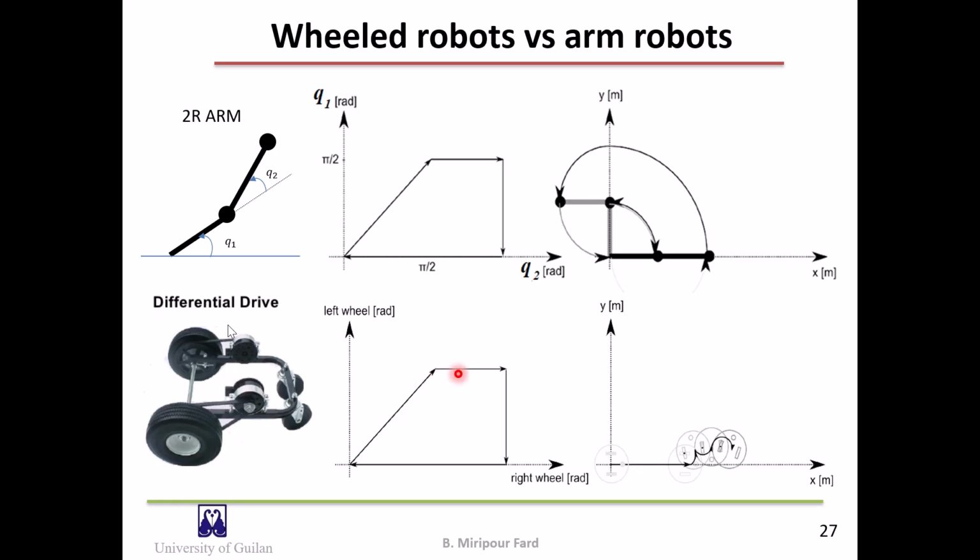Then the left wheel remains fixed and only the right wheel turns forward. Then the right wheel remains fixed and the left wheel turns backward. Finally, the right wheel turns backward, arriving at the initial encoder values, which are 0. Yet the robot does not return to its origin.